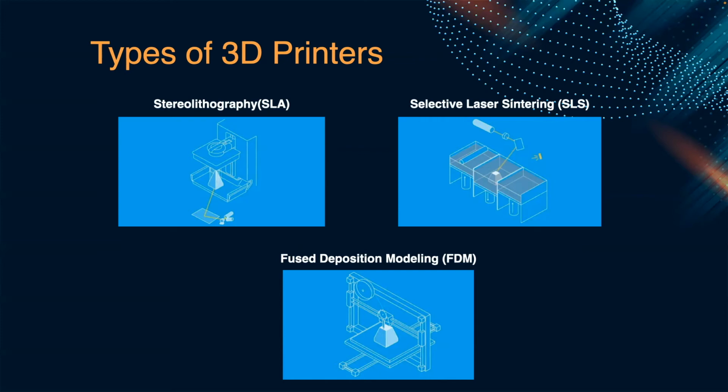Selective laser sintering 3D printers use a high power laser to sinter small particles of polymer powder into a solid structure. The unfused powder supports the part during printing and eliminates the need for dedicated support structures. This makes SLS ideal for complex geometries, including interior features, undercuts, thin walls, and negative features. Parts produced with SLS printing have excellent mechanical characteristics, with strength resembling that of injection molded parts.